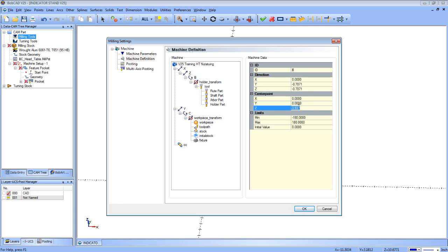And this is our rotation point number where we took the Z2 and minus the Z1 out and put those values in here. Now the travels are limited to 180 degrees positive and negative, so it doesn't hit. It can only go around to where we'll be sitting at the 90 and back the other way. So if you have limits on your rotations, you want to write those down as well. And our initial value is between those.